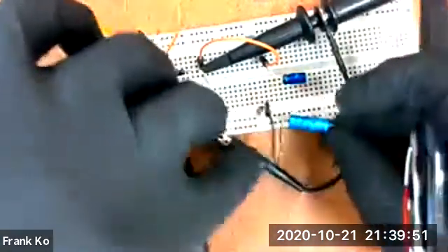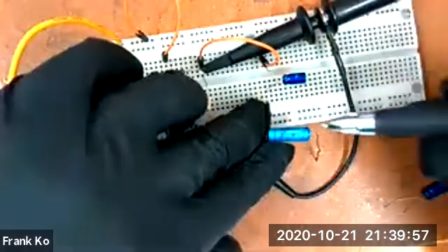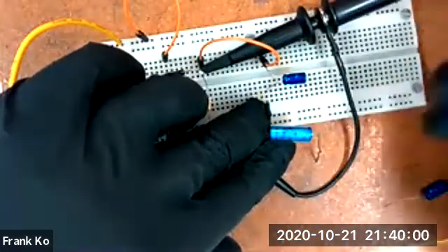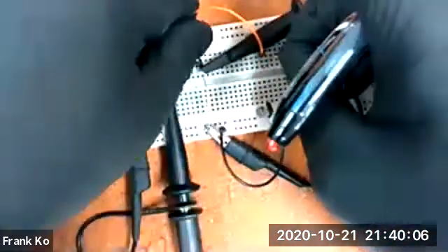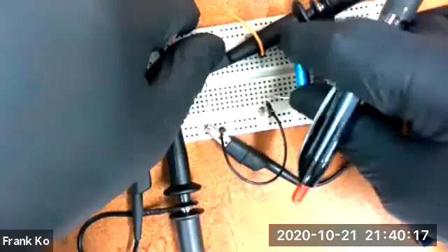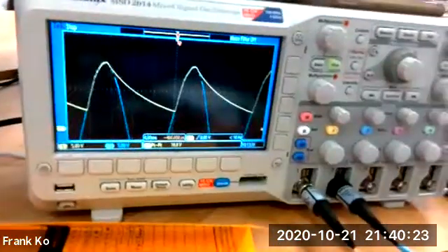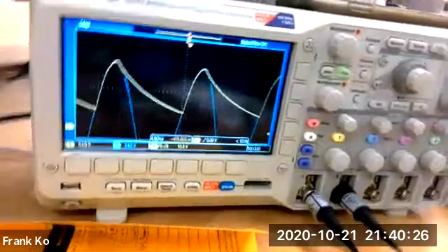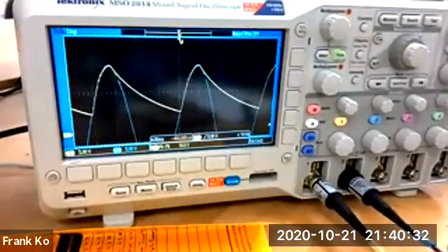Is everybody able to see that on your 47 microfarad caps? There's a little plus sign, there's a stripe for the negative. So I'm going to yank this capacitor here, put this one in its place, put one end in, put the other end in, and in doing so, your waveform will change dramatically from what I had stopped on the oscope a few moments earlier.